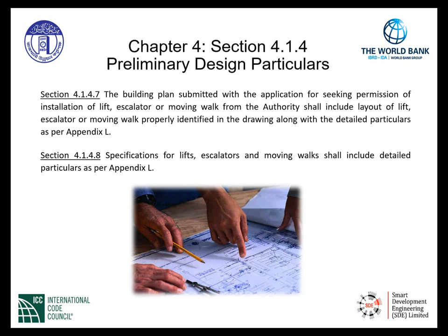Within Section 4.1.4.7, the building plans submitted with the application for seeking permission of installation of lift, escalator, or moving walk from the authority shall include a layout of the lift, the escalator, or moving walk, properly identified in the drawing along with the detailed particulars as per Appendix L. As indicated, there is a direct reference to Appendix L to be submitted with the drawings and other construction documents.